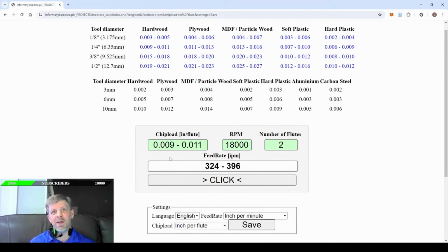And what I mean by that is, if you have a 1/8 ball nose, and let's say you're using 10% step over, you'll get significant scalping lines all the way across your raster toolpath. But then if you were to change and put in a 1/16 ball nose and run the same 10%, 10% of 1/16 is a lot less than 10% of 1/8. And so the scalping or the marks will be a lot smaller, even at the same percentage.